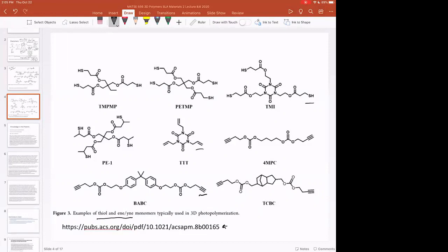And so these thiolene type resins are starting to be used more and more, especially in academic studies. So oftentimes the sulfur is hard to keep stable. It's hard to have a long shelf life in products, although there's some thiolene resins out there in the marketplace. But in academic studies, thiolene has been used for a long time.